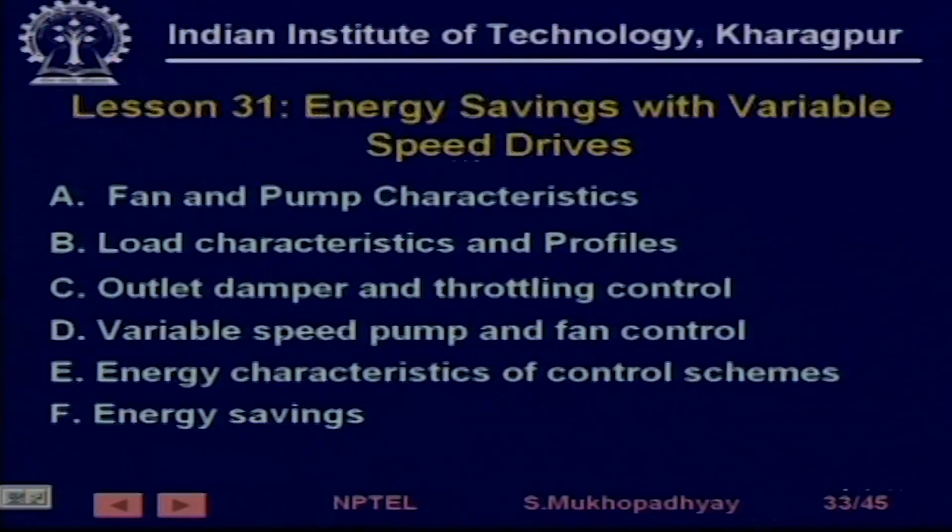After that, we took a look at electric actuators, but before taking a look at electric actuators, we first understood why there is a definite trend among industrial controls or drives, that people are going for variable speed drives. Now, what is the basic advantage of variable speed drives? We showed that variable speed drives can be huge, very significant energy savers.